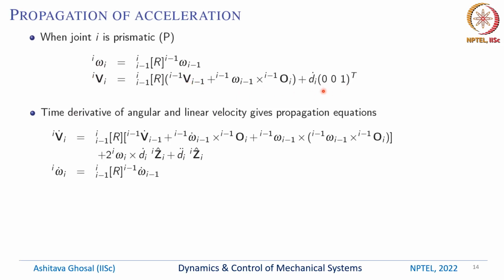Okay, what is happening at the prismatic joint? Now in the second rigid body there is some relative motion in its own coordinate system because of this d_i. So hence we will have a Coriolis term, and then we will also have the relative acceleration term, which is what shows up here. So we have some 2 omega cross v relative plus a relative.